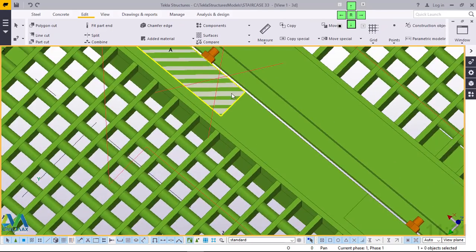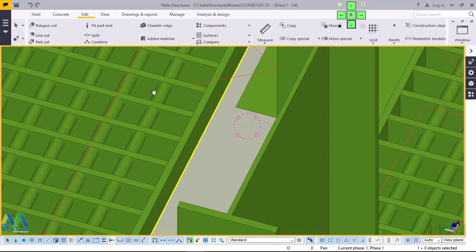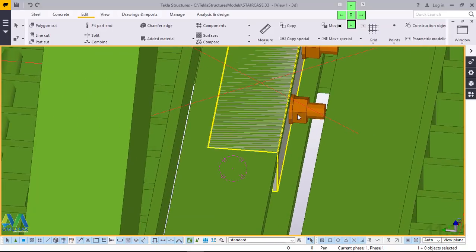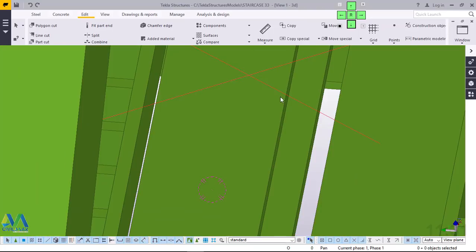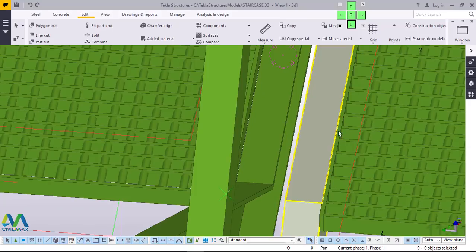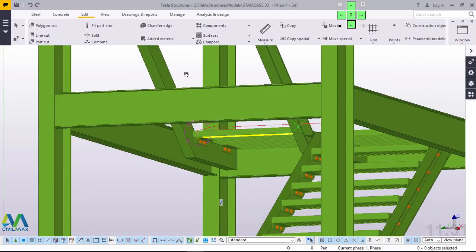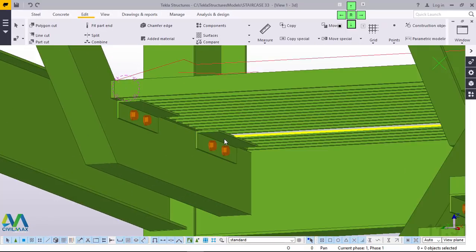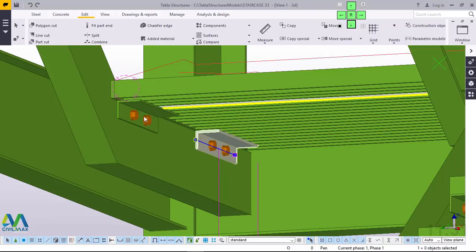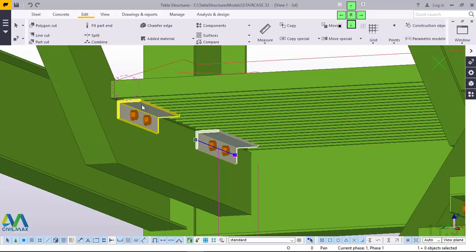We've not brought these members to the right positions where they become members of this, and that should not be a problem. What we'll do, we just get rid of this by clicking on them and deleting them away. Click this and delete. What we're going to do, we are going to select these members here. Click on that, you select everything, click on that member, click on this member, click on this member, press Control and click on this member.